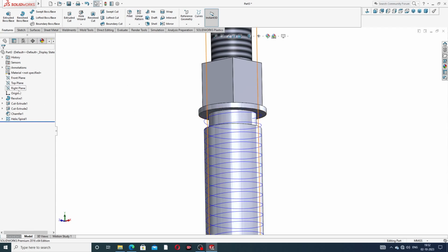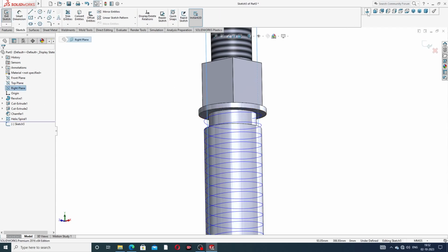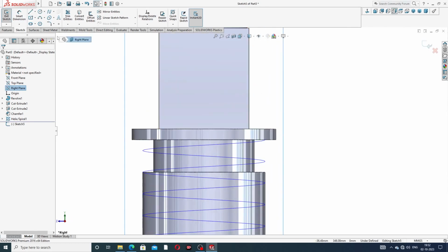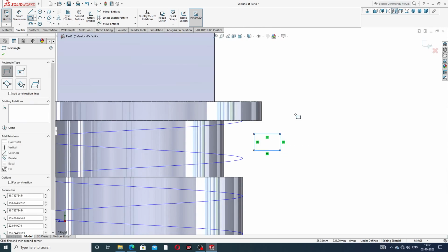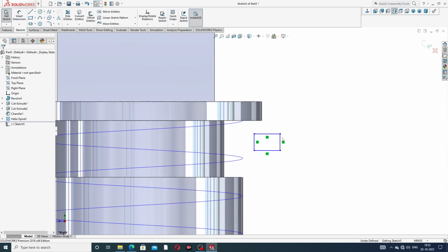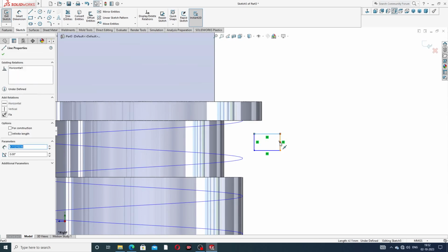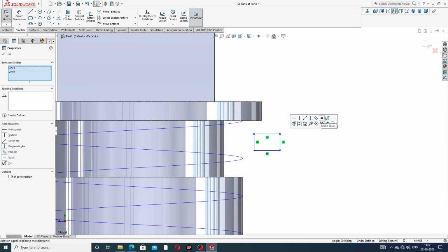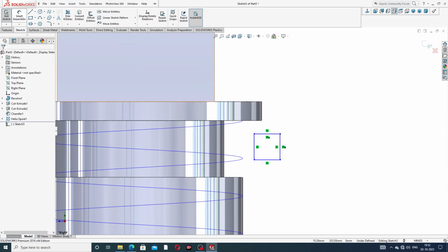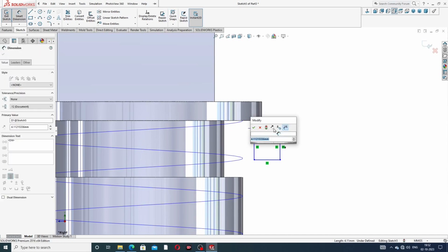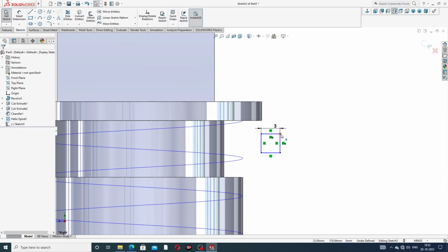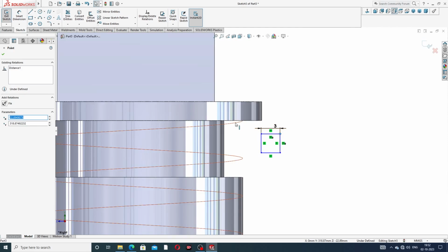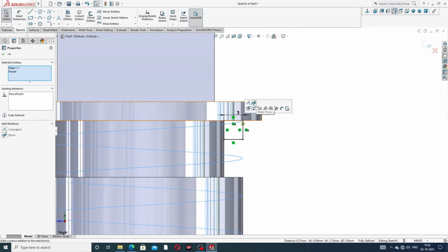Okay, use the Right Plane, Sketch Normal. Draw a corner rectangle, like this. Select here and make them equal. The dimension used here is 3 millimeter, which is perfect. All is correct. Select this point and press the Control button, and select this line here, and use Pierce.